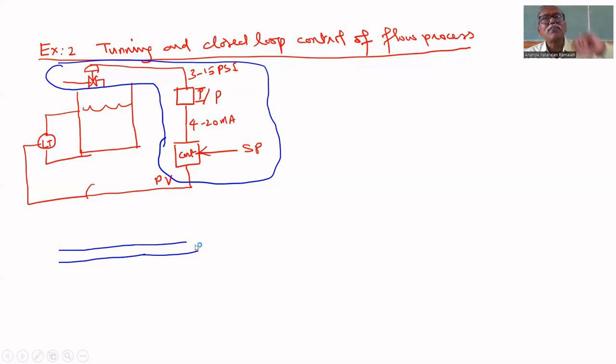Because what is the frequency of power supply? 50 hertz. That's why it should rotate at a constant speed. Then only you will get 50 hertz. Otherwise, you won't get 50 hertz. So, irrespective of load, it should rotate at the same speed. That's why a controller is required. So, that will adjust, suppose the generator is run by diesel, the diesel flow rate.